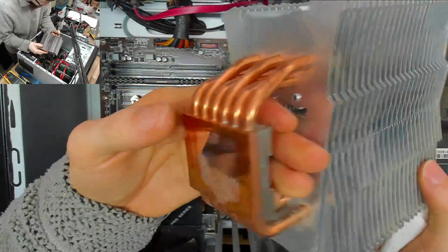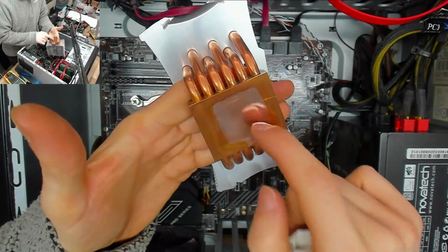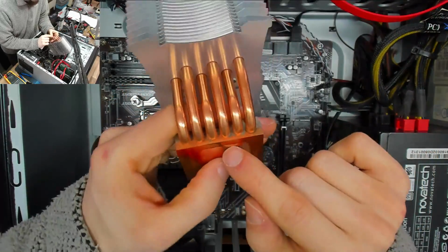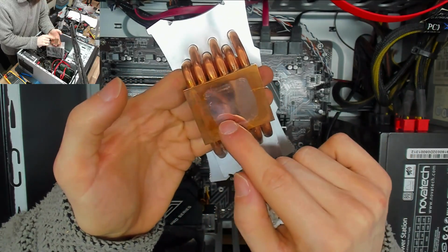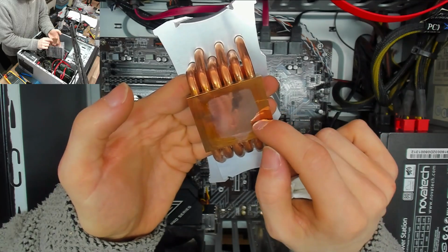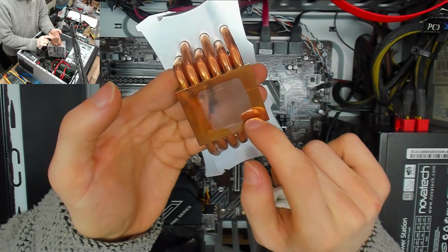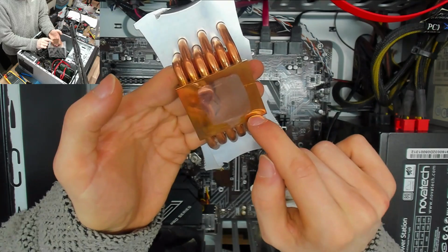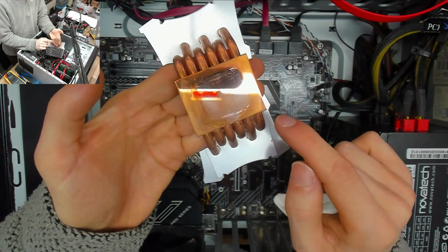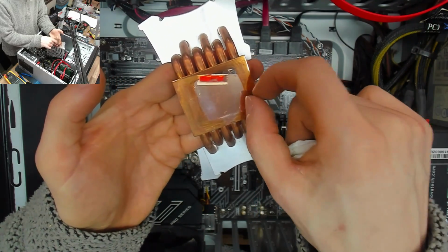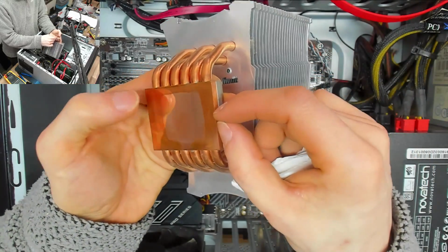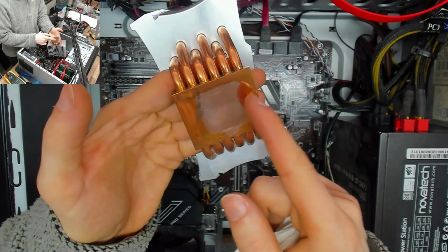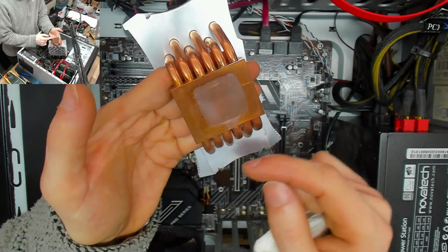It's also worth noting that this looks like a really wonderful mirror finish, but don't be deceived by these. Most likely this was machined, and then it was probably tin plated or copper plated. So this hasn't been lapped to a shine, it's just been plated. And that means you don't actually get any benefit, because you've got to go through the plating, and then there's another interface between the plating and the actual core of the heatsink. So this kind of mirror finish isn't necessarily a good thing.